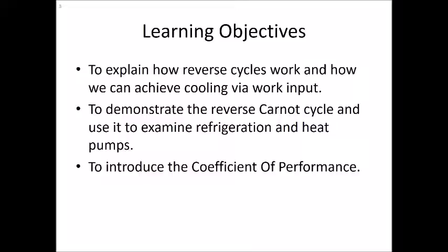It is a fluid that undergoes a phase change whilst exchanging heat and work with its surroundings, and we need to find the appropriate data in order to calculate the energy that's being exchanged, just like we would do in a power station application for a forward cycle. So we're going to look at how reverse cycles work and how we can get cooling from work input, or really heat transfer from work input.